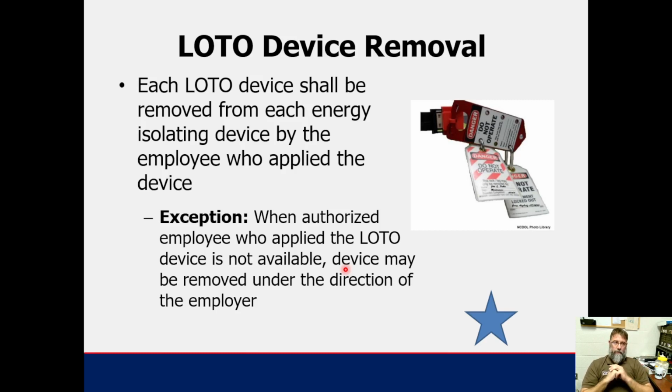So keep that in mind. Lockout tagout is for an individual's safety. It has nothing to do with the safety of the machine. There could be somebody working inside that machine that you don't know is there. And if you operate that machine, you can either injure or kill another employee. So keep that in mind.